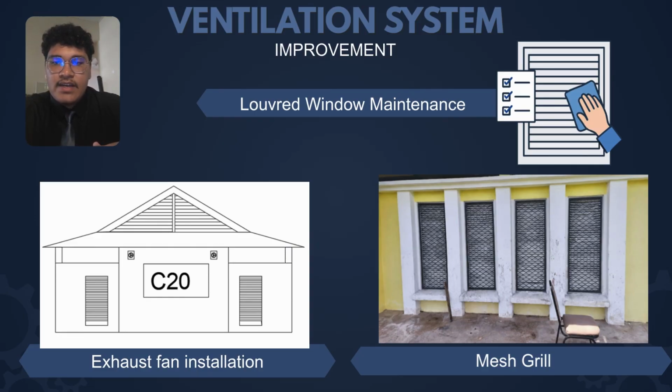After that, the exhaust fan installation. The purpose of mounting two new exhaust fans high on the center wall panel is an effective, practical upgrade for the facility. Since hot air, steam, and odors from players after training naturally rise, installing the mechanical exhaust fan at the highest possible point ensures that they actively pull out the stagnant humid air layers before they can settle over the cubicles.